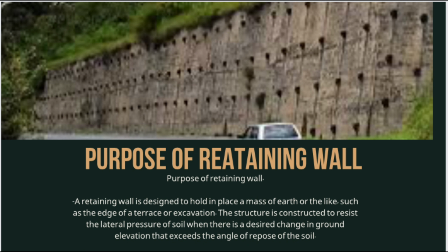So, its purpose is to hold in place the mass of earth or soil. The structure also resists the lateral pressure of soil. We know that resisting lateral pressure is very crucial, because the pressure is exerted in a horizontal direction. So it is important because it affects the consolidation behavior and strength of the soil. So the main purpose of the retaining wall, guys, is to make things safe and to prevent landslides